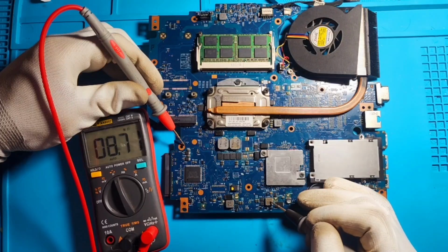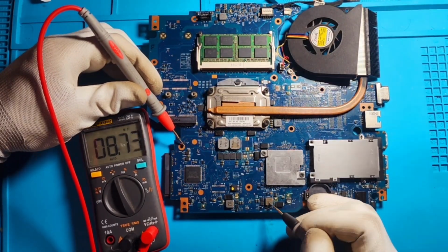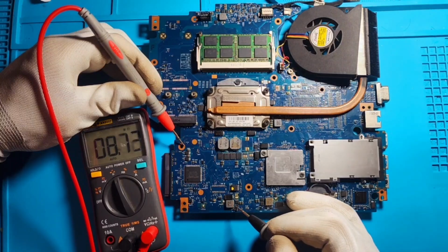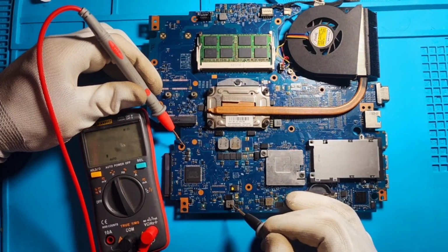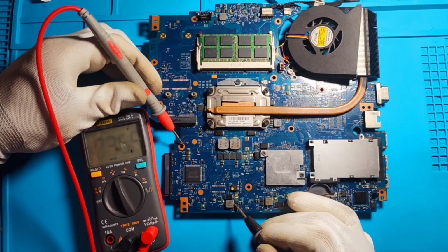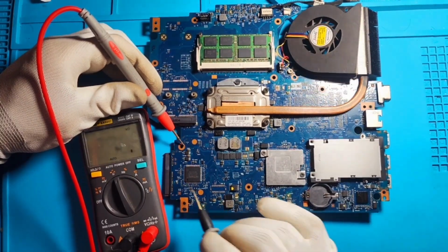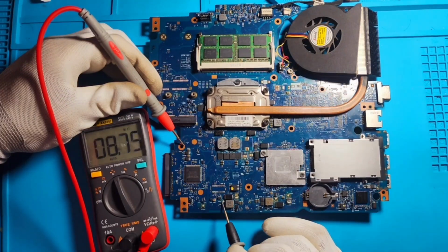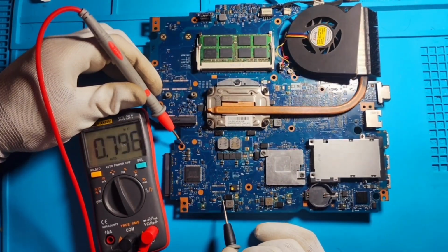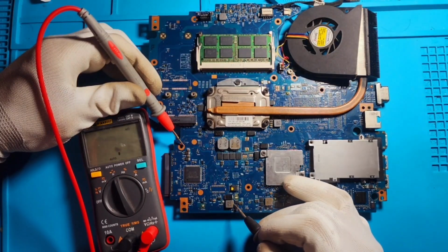The 3.3 volt coil is having a higher resistance, and the coil on the 5 volt is having a low resistance, so we have to check these points. We are blessed with the jumpers here, so we can remove those jumpers and isolate the sections and identify the area that is causing this coil to show low resistance.